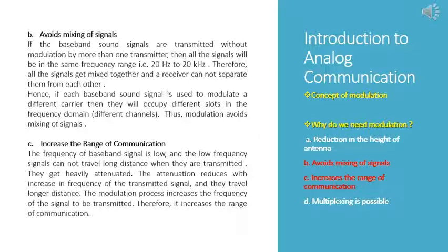Here, the frequency of the baseband signal is very low, as we know. It's around 20 hertz to 20 kilohertz, and these low frequency signals cannot travel a long distance. When they are transmitted, they get heavily attenuated. For example, I gave an example a few minutes ago about throwing a paper about 100 meters, and the paper is so light that we cannot send it by throwing it by itself.